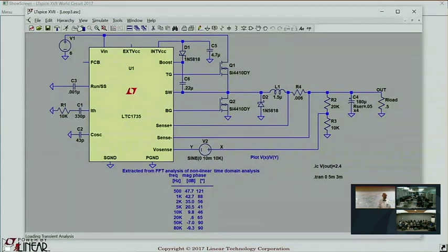I can't make equations for component values if it's stable for all values. Now, what's the limit for that picture to be correct? The limit is that it's possible to look at in the frequency domain, which means that you roll off the transfer function well below the Nyquist frequency. So as soon as you look at this problem below the Nyquist frequency, you've thrown away where the stability problems are.